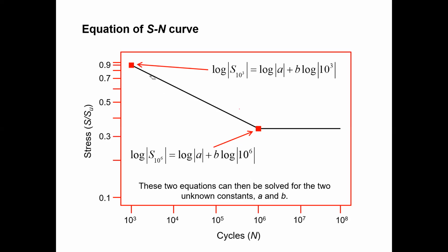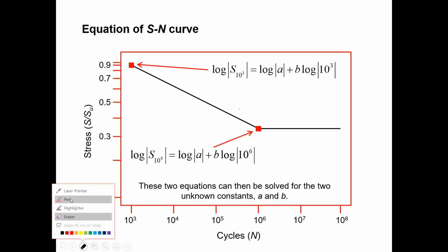During this curve, we are not going to change the stress pattern. We will apply the same stress, and during this number of cycles that stress pattern will not change. If you increase the stress again, this curve is not valid anymore. So this curve is for one applied stress, one stress curve.